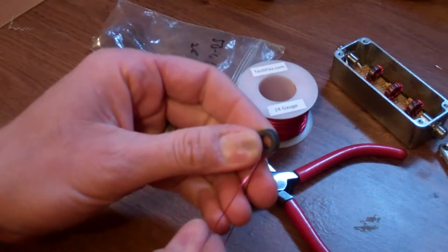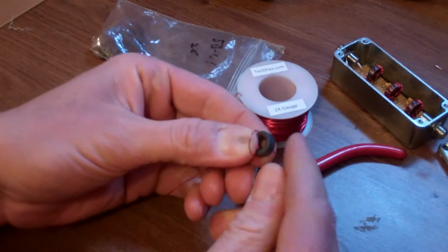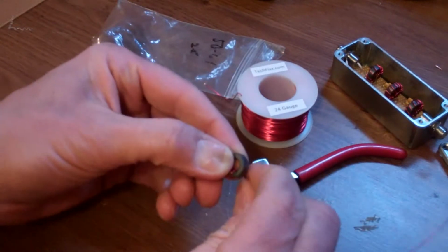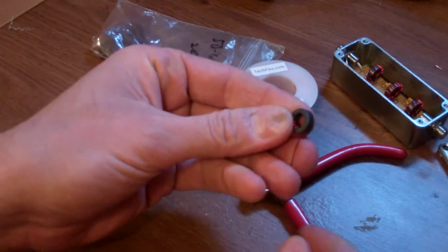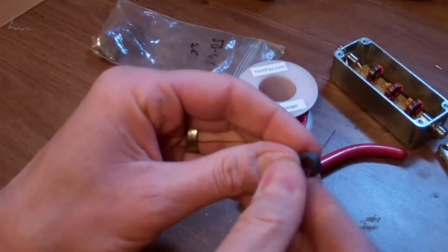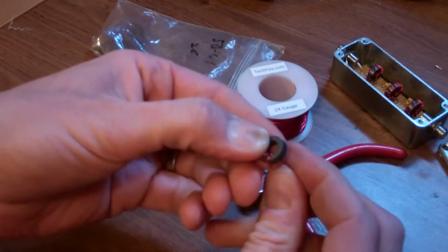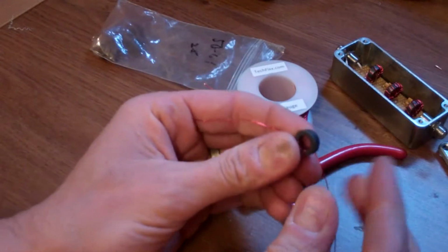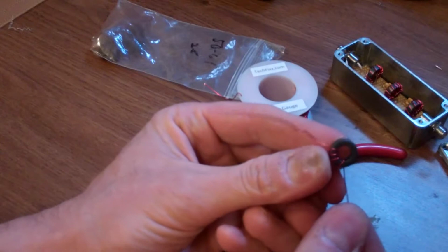So I just continue on from there. It's kind of like sewing a little bit, but you make sure they're snug. You want to pull them tight. Each time you pull it through, you want to pull it really tight so it snugs up and is close to the ferrite. You also have to be a little careful that you don't rub or scratch the coating on the wire, because this type of ferrite, and some other types, can be semiconductors.